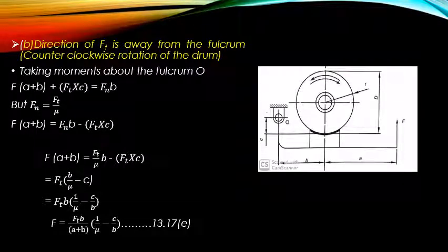Now for the third case, if we consider the counterclockwise rotation of the drum. So what happens? For clockwise rotation of the drum, Ft was moving towards the fulcrum. Now for counterclockwise rotation of the drum, Ft is moving away from the fulcrum.